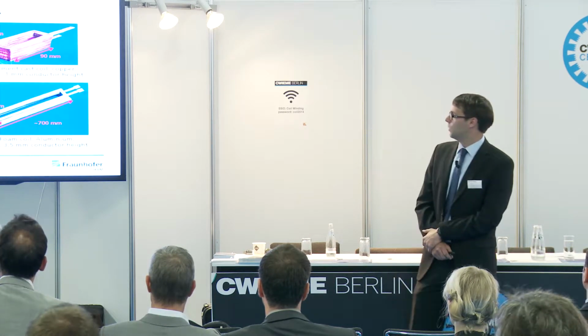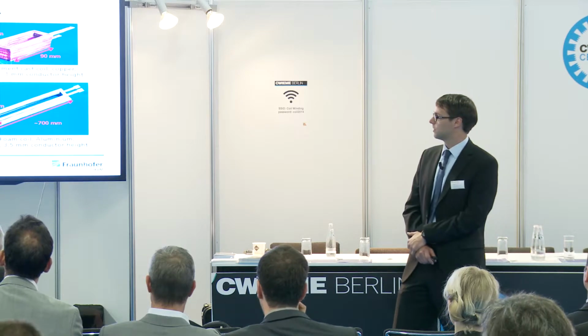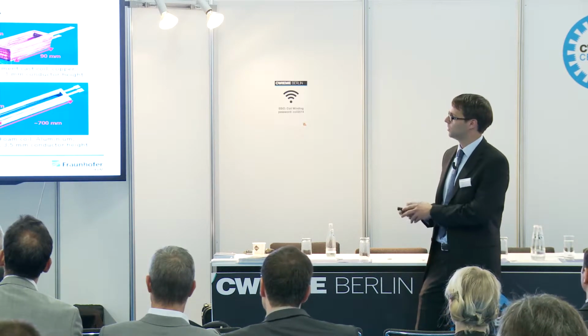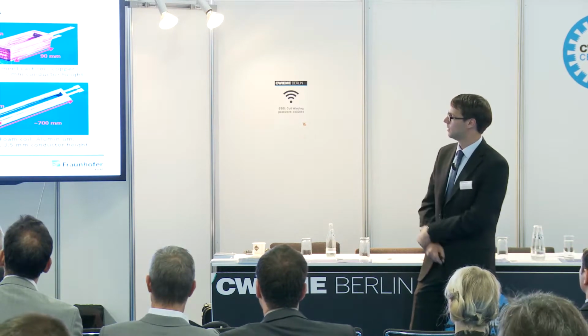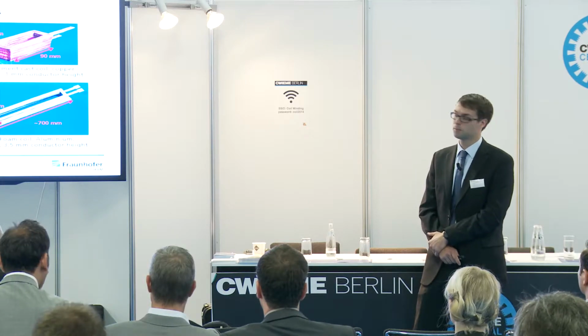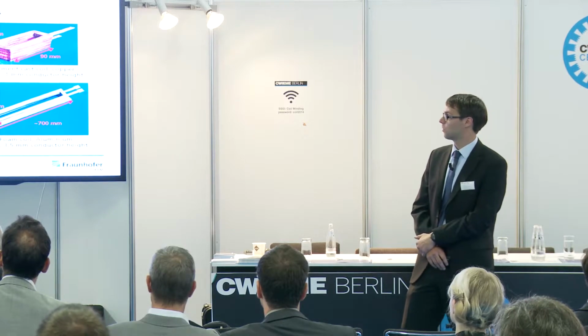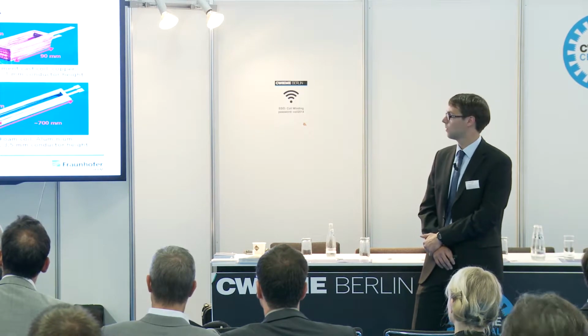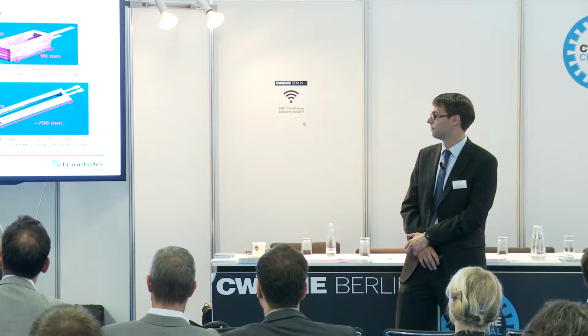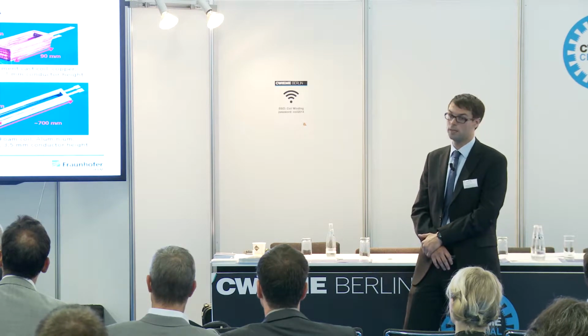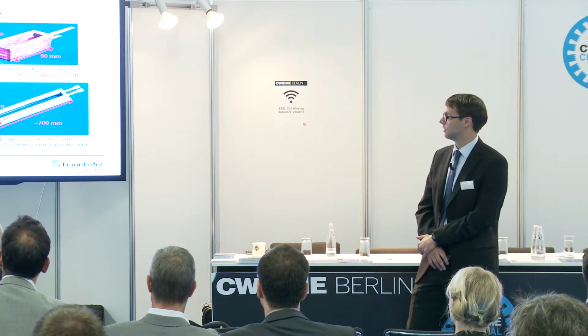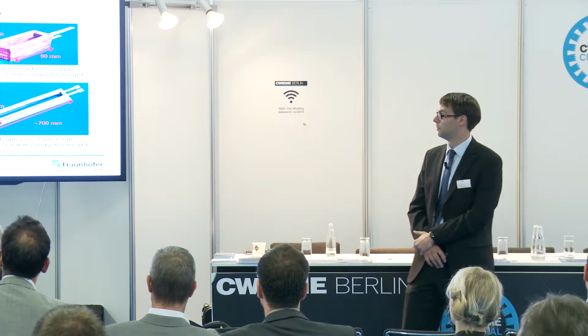We can realize these coils in different casting processes. The most suitable process for prototypes and small series is the investment casting process, also called lost wax casting in literature, for small coils up to 200 millimeter length. We can realize conductor heights down to 0.8 millimeters and conductor areas of 4 square millimeters.